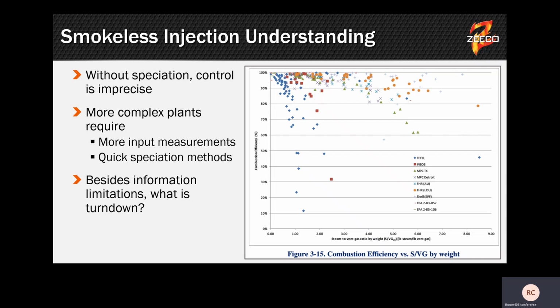Primarily, what's the composition of the gas? Different gases and different compositions require different steam and air inputs for smoke mitigation. But other than that, there's where this flare is being operated in its range, and what the technology is, and other aspects. And so while this is the absolute most common method for controlling steam or air injection, a ratio control, it's also one of the least accurate.